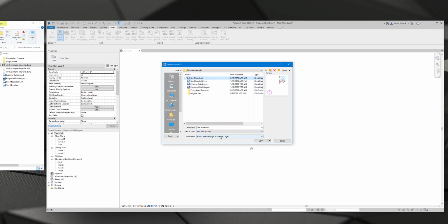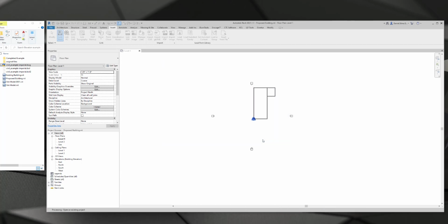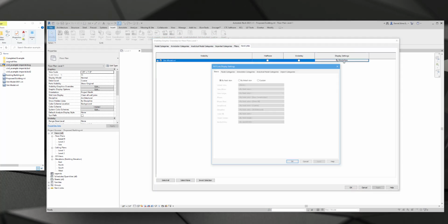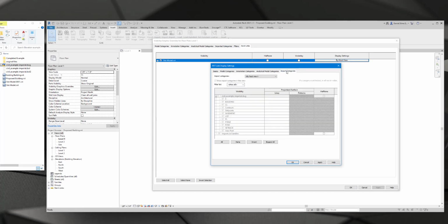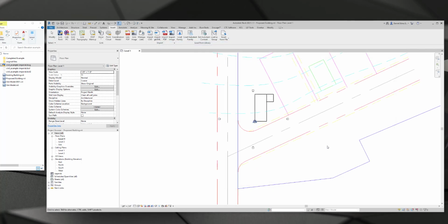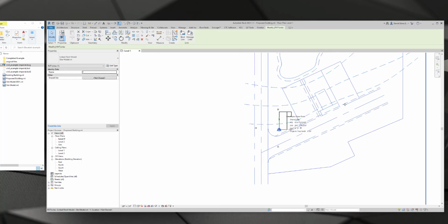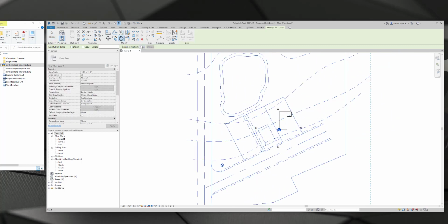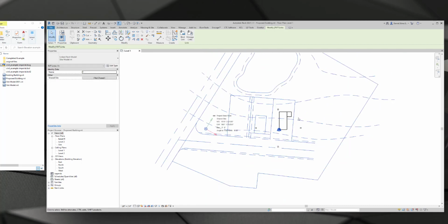Can't do shared coordinates yet because we haven't set that up here. And we're doing it this way because BIM 360 doesn't allow publishing coordinates. We can only acquire coordinates. For this link, I have to quickly turn on the linked DWG in that Revit site file. It doesn't show up by default. And so here we just simply, like the previous video, where we weren't talking about elevation, we sort of position the building where we want it.